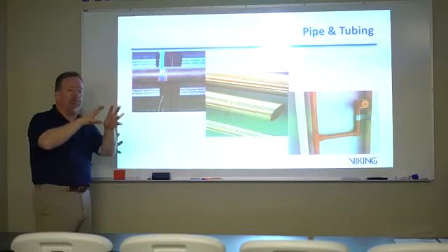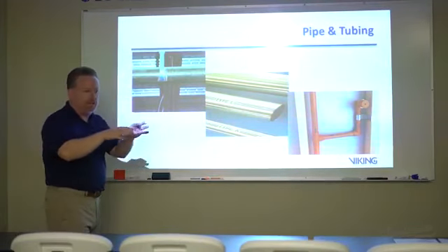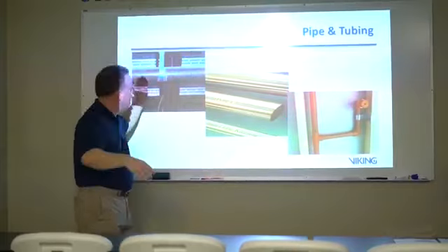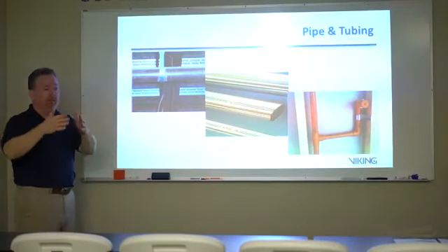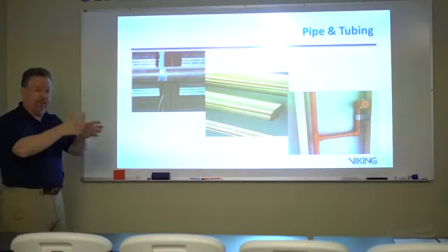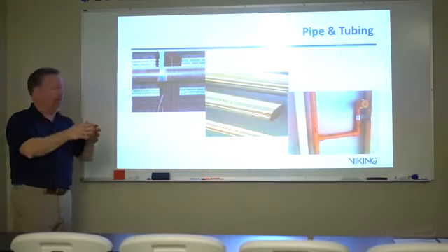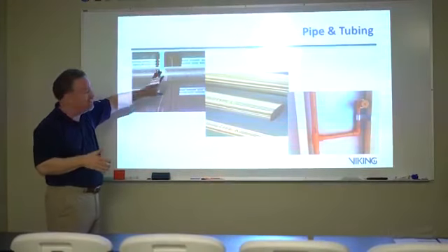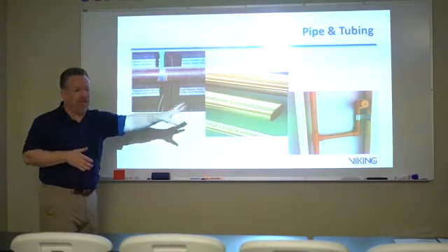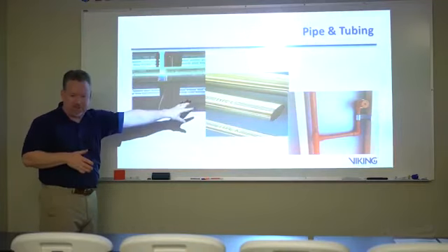So you're going to lose pressure by what we call friction loss. Simply by water flowing past the walls of this piping, it will lose pressure. And it will lose pressure at a specific rate that you can calculate. All right? So one of the things we have to be careful of is that each of these different types of piping have different friction loss characteristics.